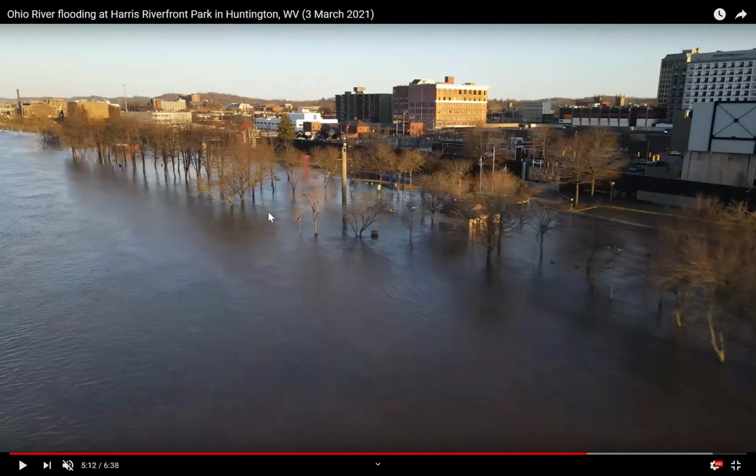And so in the center of the channel, the water at the surface has very little resistance because it's far from the edges, and those edge effects are where resistance is applied, and it's far from the bottom. So the water is moving swiftly through the center of the channel, but moving very slowly on the floodplain because of all the debris. Let me play this again.